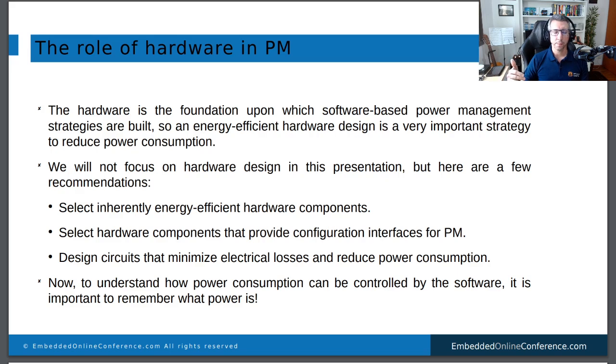That means selecting components that are power efficient. For example, the CPU architecture. Between x86 and ARM, ARM is probably a better option in terms of power management and power consumption. x86 processors are usually focused on throughput, on processing power. So you might think about that.